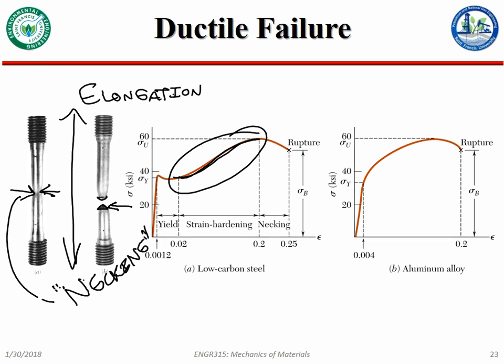We cool with that? Actually, let me explain that a little bit more. So like, if I strain a material out to here, say, and then I stop and I release all the stress on it, it'll travel along a line that is defined by the elastic modulus.